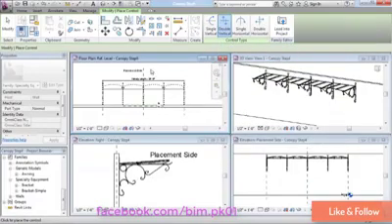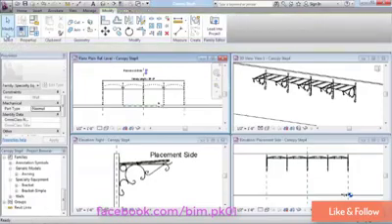And you don't get any real indication from the mouse other than this little tooltip that says click to place the control. So I would prefer a cursor change of some kind, but just click and that will actually place the double arrow control. And be careful not to click a second time because it will actually create another control. Instead, just cancel out of the command or click the Modify tool to complete it.